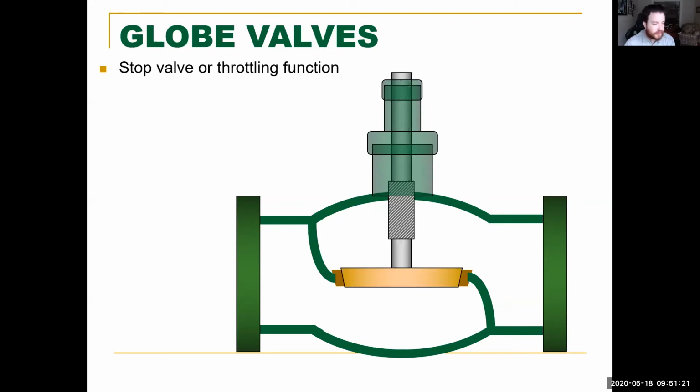These things are used in a lot of older ships, and they're being phased out and turned into butterfly valves because they take up less space. But these are fantastic valves for what they are, because all the flow comes up around underneath them. And they can easily be repaired. That's what makes these valves so great. You could take this entire valve apart, this whole top piece here, and just take it right off.